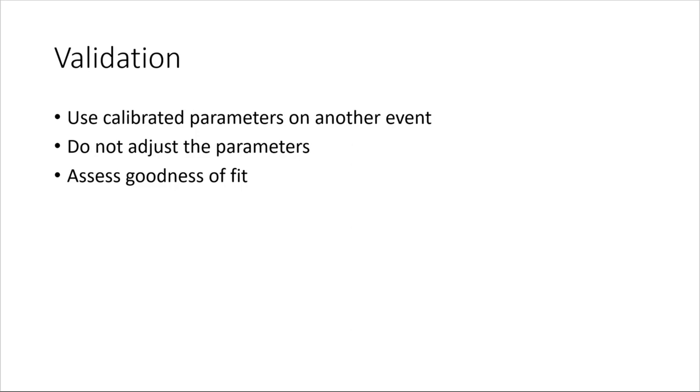The only parameters that might change in a situation like this are initial conditions, for example, initial deficit, initial base flow, and so on. Things like constant rate, unit hydrograph parameters, base flow coefficients, and so on should not change. The best way to represent the performance of a model for general use is to report its validation statistics.